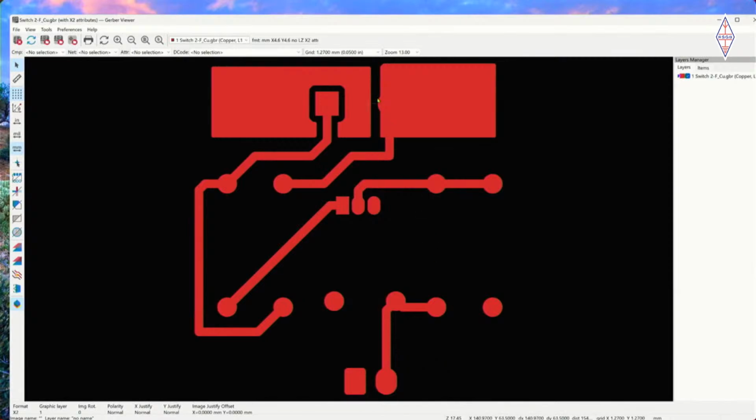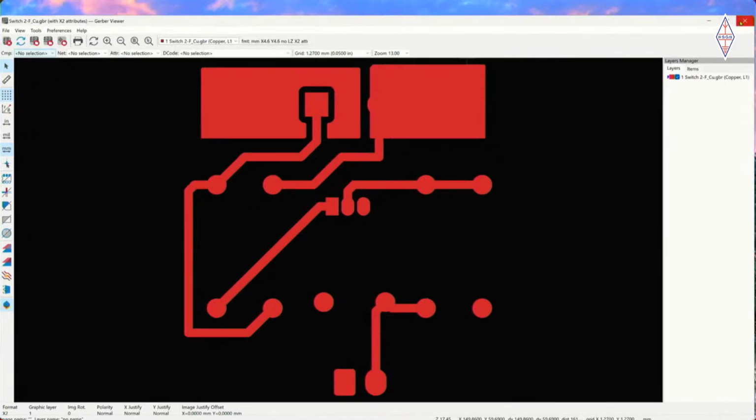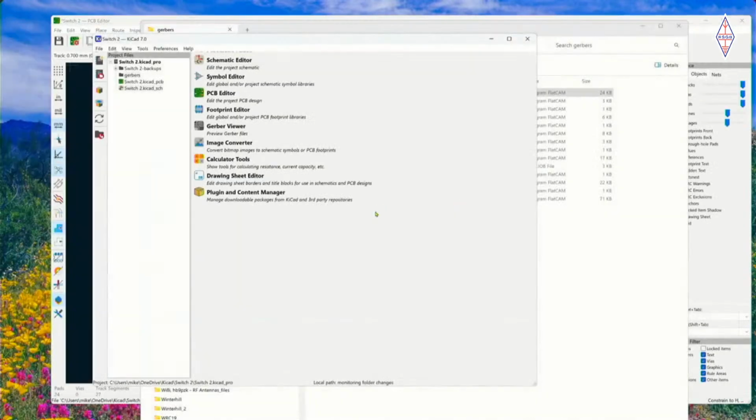And you see this funny little thing here. Now that's not quite the same height as that, so we can go back to our PCB and maybe make it look a little bit neater if we wanted to. That's the OCD bit again, isn't it? Exactly, make it look neat. Well, actually, in this case, there's going to be 50 volts between these two points. So we do want to make them a little bit better spaced potentially, but of course we're limited by the spacing on the chip itself. On the TO220, and that should be more than enough, really. And of course, if we were doing this as an RF design, that could be even more important, because it could add, say, capacitance between two tracks and things like that.